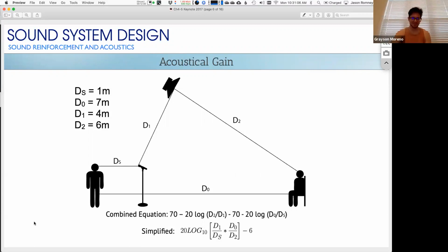Mic drop. Right? Because we can either consider that variable or not consider that variable, and we can get the same answer. Okay? It doesn't matter how loud they talk. Your gain is the same. How many times have you blamed a poor actor for your gain before feedback problems, when in reality you just had a crappy sound system? Okay? Your gain is not their fault. Okay?